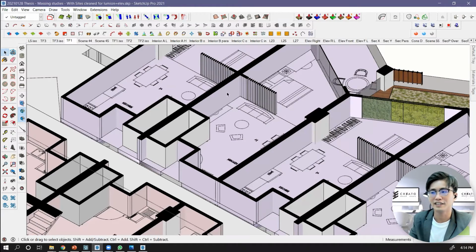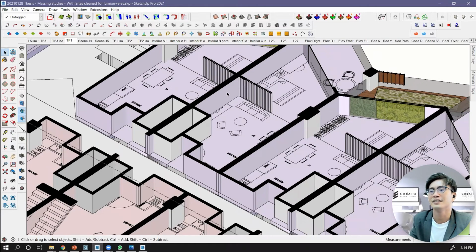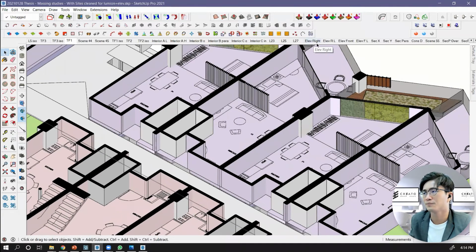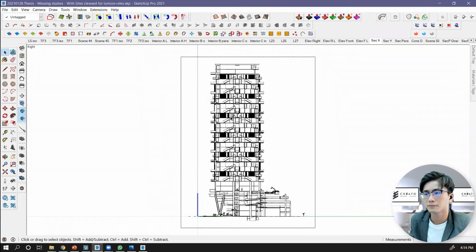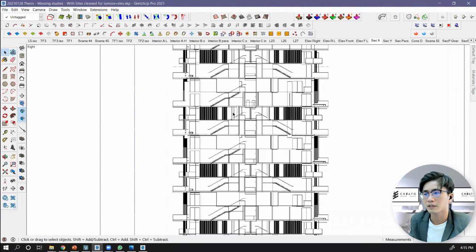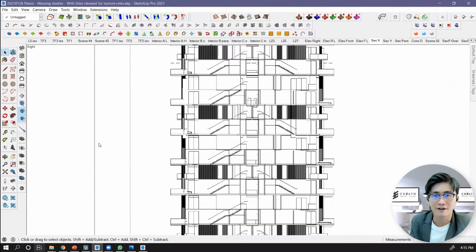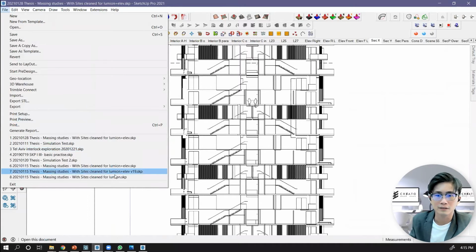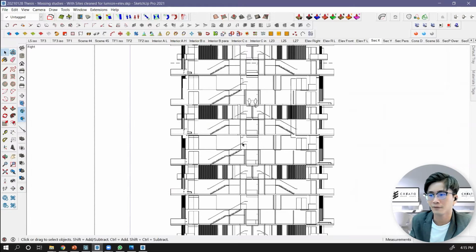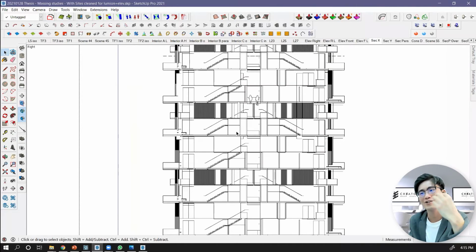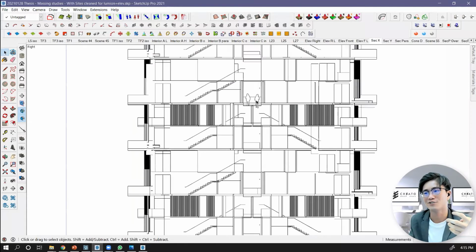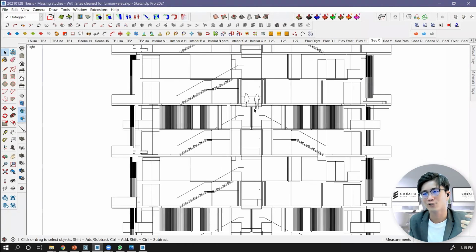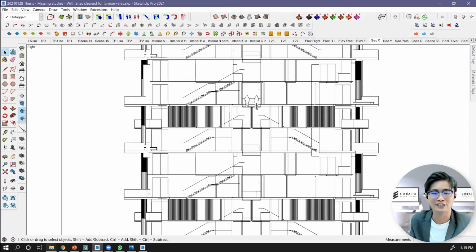Yeah, this solves a lot of problems when you are drawing. And also in elevation, as you can see, I go to... maybe not this. I show another file maybe later. Construction detail, because even in elevation I also can create drawings. Okay, let's say for this human figure, it's also like a 2D human figure, but we can place it in the elevations.